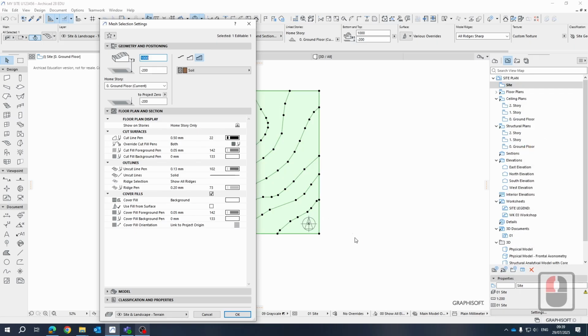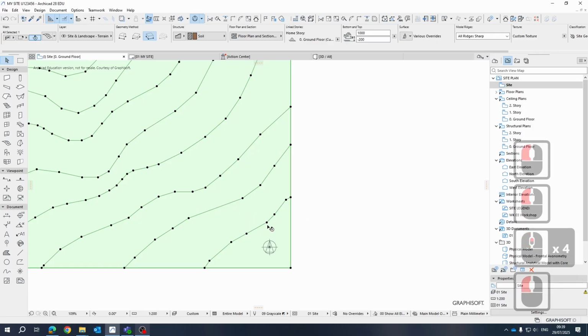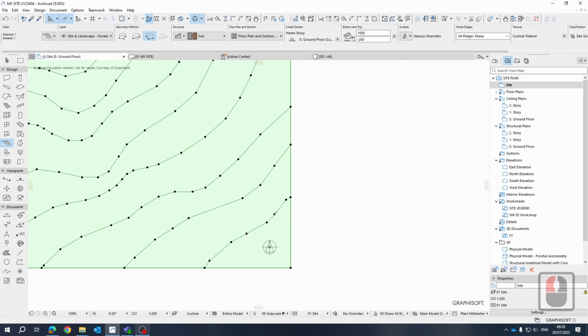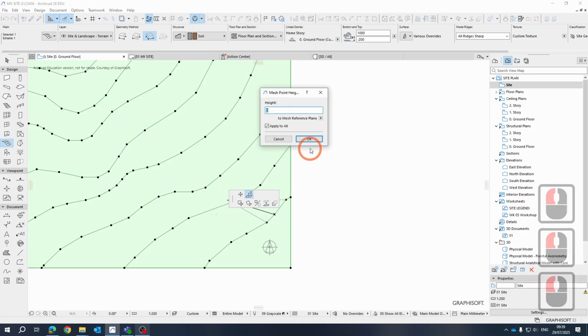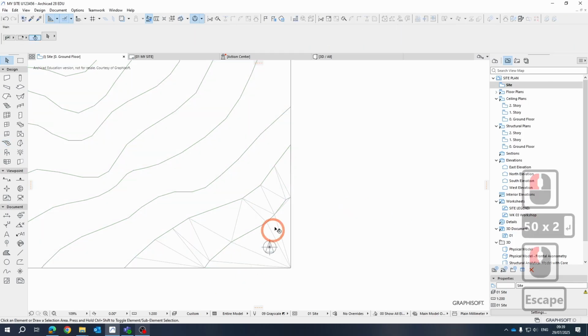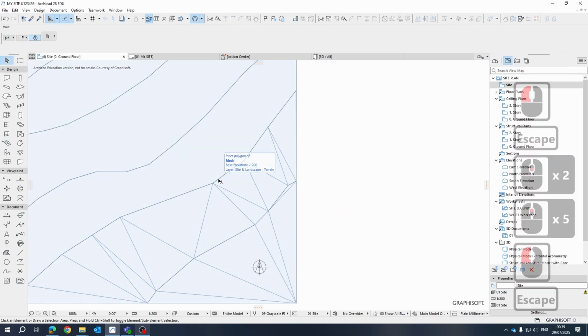When you create a surface with these ridge lines, when you start extruding them now, so if I pick this ridge line and I change the Z values, so in the edit tool, select, we're going to change the Z, and I know that this must be 500 above. Okay, so now you can see it's starting to create these triangulation lines.